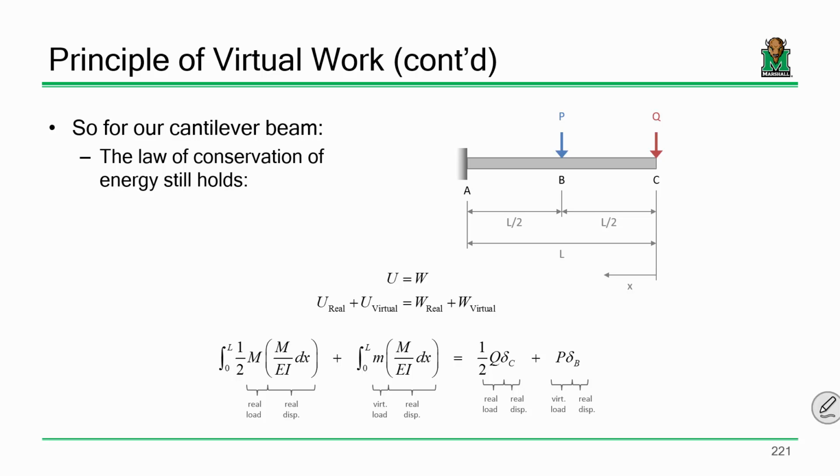Now, the nice part is our formulation down here. Look at this. We've got differences between real load and virtual load, but they're all functions of the real displacement. See that? Real load times real displacement. Virtual load times real displacement.